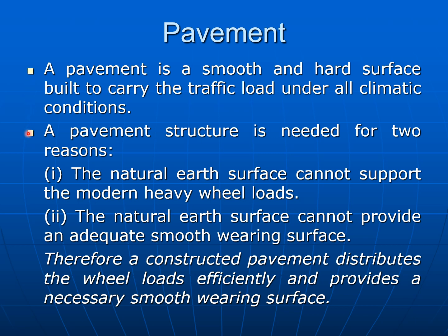A pavement structure is needed for two reasons. Number one, the natural earth surface cannot support the modern heavy wheel loads. Number two, the natural earth surface cannot provide an adequate smooth wearing surface. Therefore, a constructed pavement distributes the wheel loads efficiently and provides a necessary smooth wearing surface.